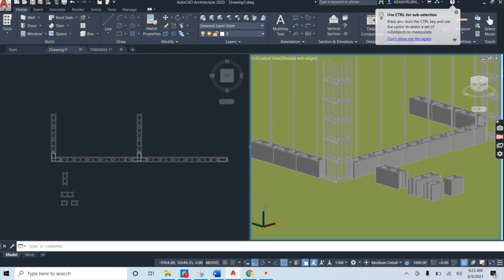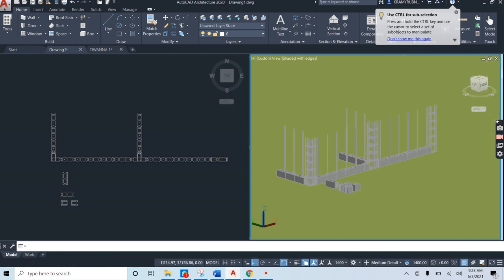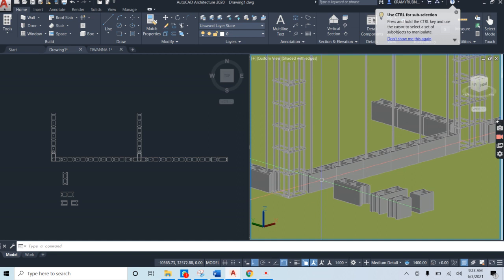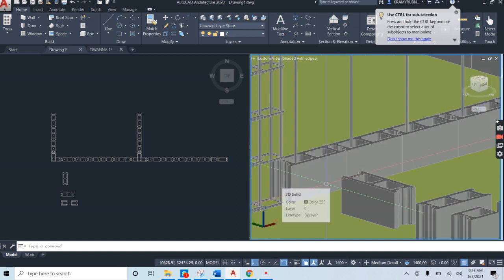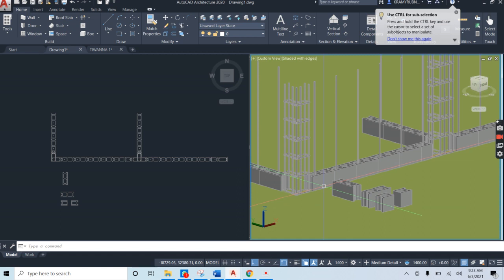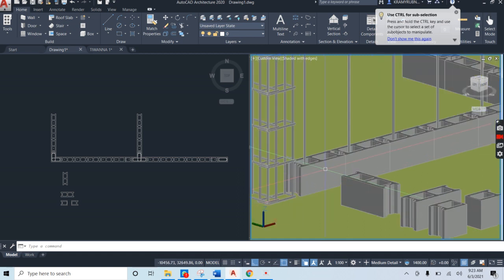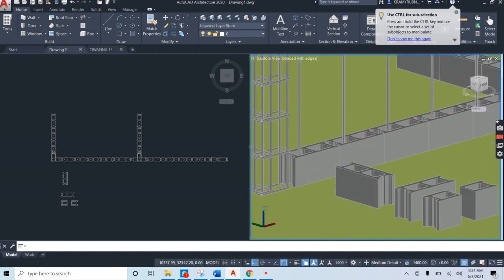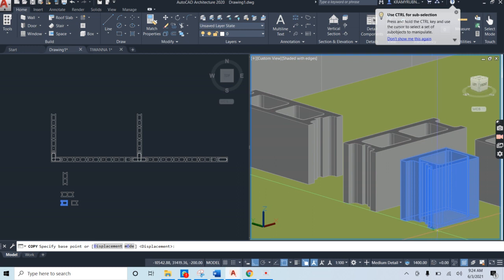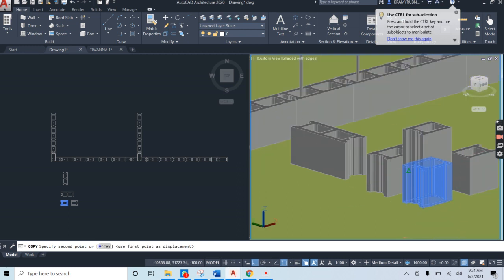What I would advocate you do before you pour your concrete for your stiffeners though, is to continue with the laying of blocks. But one has to be careful, because blocks are not laid with straight joints. The joints have to alternate. For example, this first row started with a complete block. It means my other row is going to be starting with a half block. And that's why we needed half blocks.